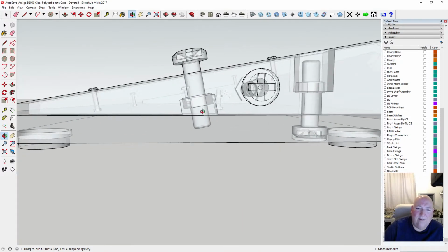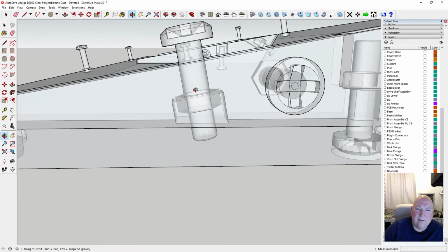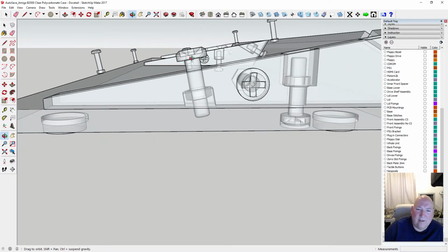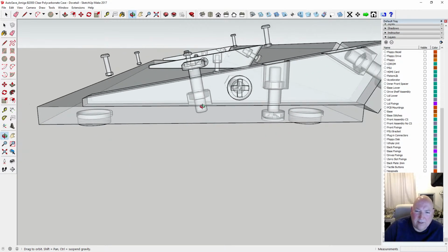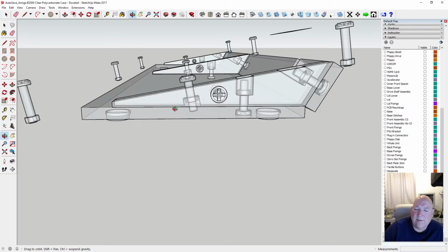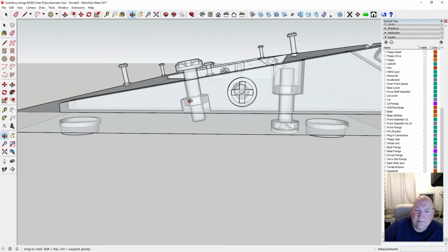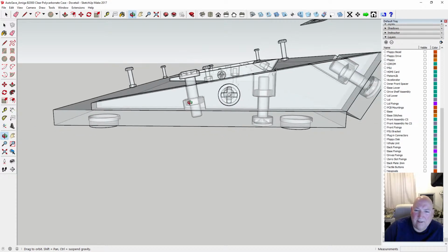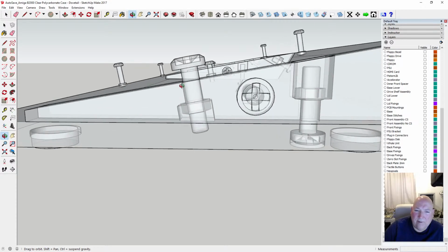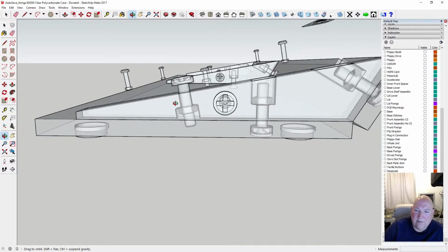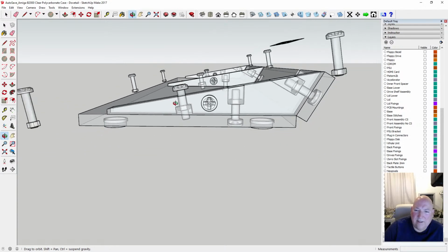Yeah, because I could have used a smaller bolt. I think that I used the smallest one I had, and it's still sticking through just a bit. So what it needs is a deeper well here. But if you do make a deeper well, then you've got less material, you've got easier chance of cracking. See, if that one was over here, I could do a deeper well.